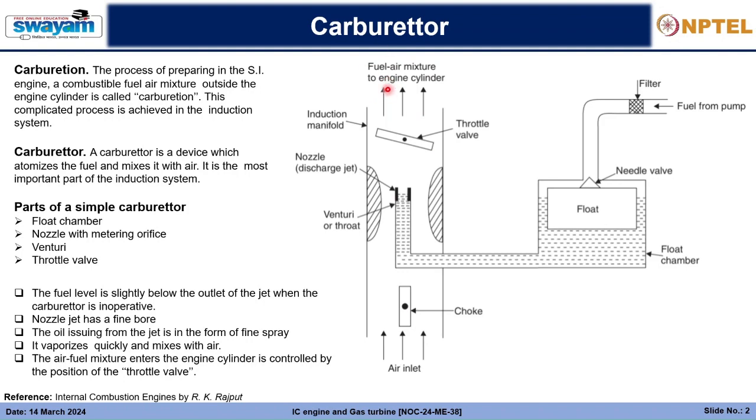As this air fuel mixture is required in the piston engine cylinders, there will be a piston engine cylinder, and there you will have to give a charge, and due to the ignition caused by the spark plug, the combustion will happen, and accordingly the whole process will continue in a spark ignition engine, and that we know till now. And that mixture, the fuel air mixture, is prepared by these carburetors at a precise amount which is required by the engine, and that process of preparing the perfect amount of air fuel mixture is called carburation.